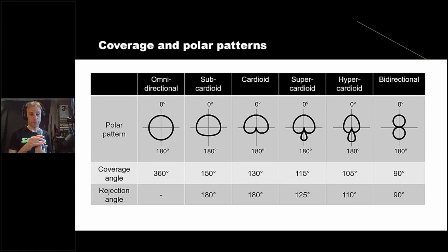But for illustrative purposes, you can see now as I start going around to the side, this sound starts dropping off a lot faster. I have to remember to stay in the pattern here so you can actually hear me when I do that. So again, a supercardioid pattern is even tighter than the cardioid pattern is. So what that means is that the drop off happens much quicker as you start spinning away from the mic. So when you're 90 degrees off axis, you're already like 10 dB down, and you can hear that drop pretty dramatically when you're down here.